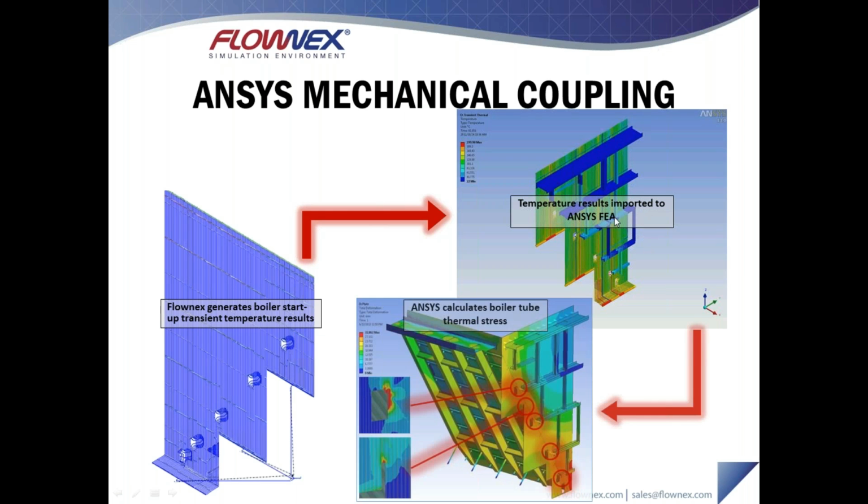as a whole. We're then able to highlight areas of high stress and either look at redesigning the geometry in these areas to avoid stress concentration, or perhaps even altering our startup protocols. So perhaps ramping the boiler up a little bit slower or a little bit faster, and seeing what effect that has on the thermal stresses inside of the system as a whole.